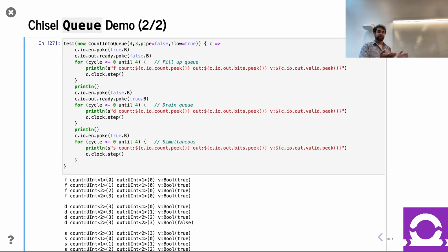So you're saying, wait a second. Let's talk about this, right? This means that you have a queue, which was implemented as a FIFO of registers, and you're saying the queue is empty, but someone's sending and someone's receiving. We can just bypass the queue combinationally. So there are certain implications for this, right? Depending on how our design is set up, this could potentially become a critical path, which is why it's not the default behavior to turn it on.